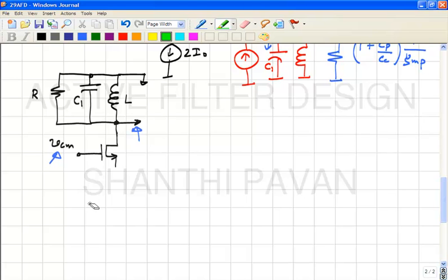Finite output impedance, but more importantly, there is also going to be parasitic capacitance here. So, this finite output impedance as well as some parasitic capacitance, which you cannot avoid. So, even though you think that the current is 0, there is in fact some current because of the parasitic impedance at the source node. Please note, this is the common mode impedance at the source node, right.